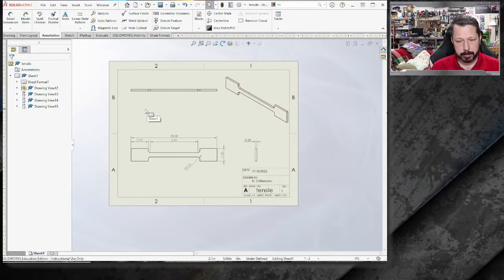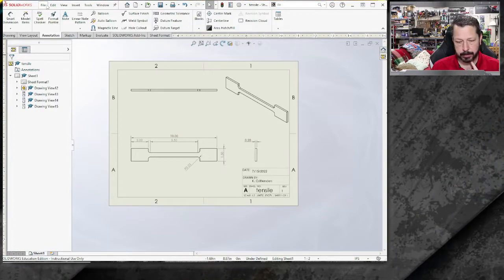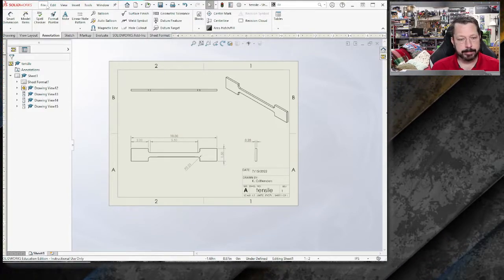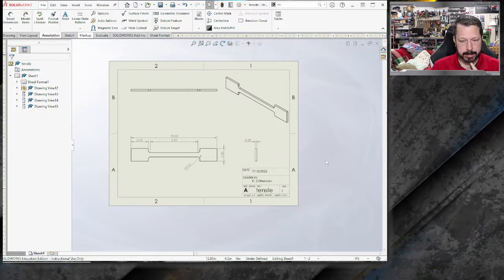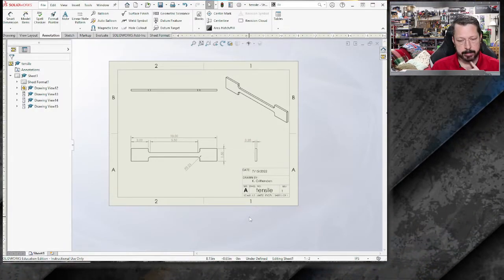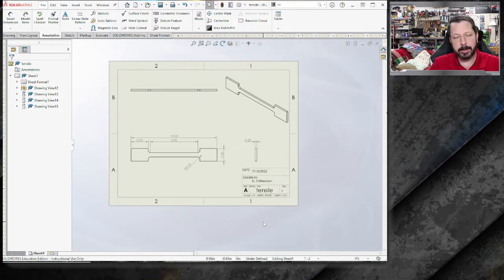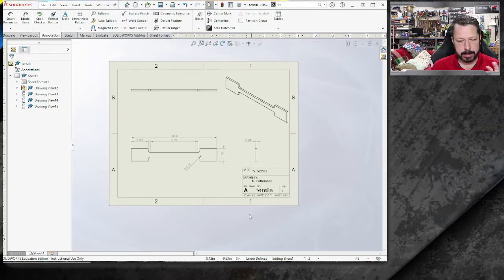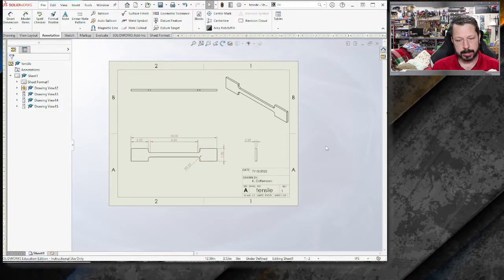Okay, that would be more or less what you could turn in. Then you could file, save, print, whatever you wanted to do. You could print it as a PDF to include in a separate document or whatever. And that would be the most direct route to create a reasonable drawing. It doesn't have all that title block that you don't need. It has just what you need on there, the views that you want and the dimensions that you want on the document.